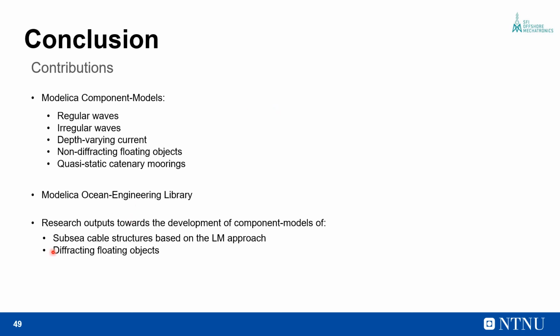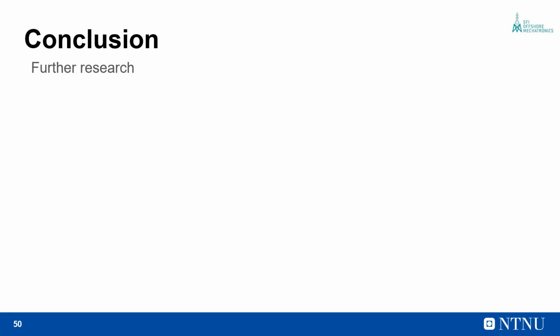We also present research outputs towards the development of component models for subsea cable structures based on the lumped mass approach, and for component models for simulating the hydrodynamics of diffracting floating objects. We also present a co-simulation methodology for tensioned risers and demonstrate its effectiveness.